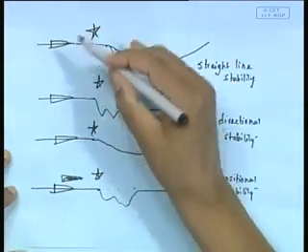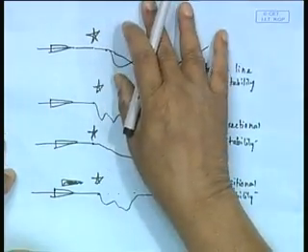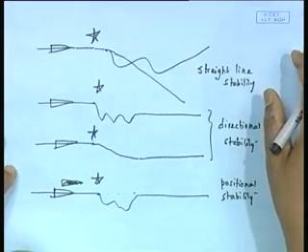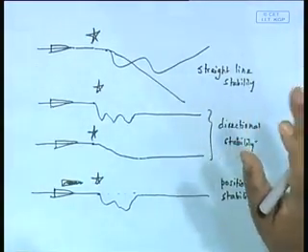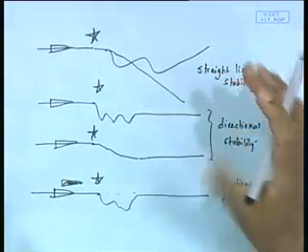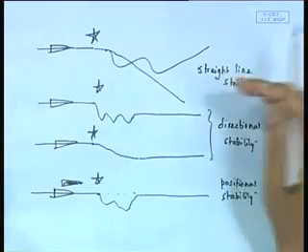So naturally, when we are studying this initially, what we are going to talk about is developing an equation of motion, to find out, when the ship is disturbed, what kind of forces get created on it. This is similar to what we talked about in roll, because we said that as soon as I heel the ship by theta degrees, we look at the moments created because of hydrostatic pressure.